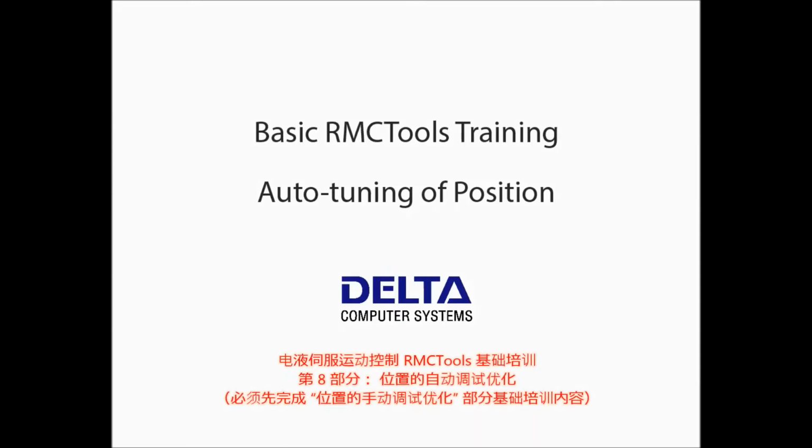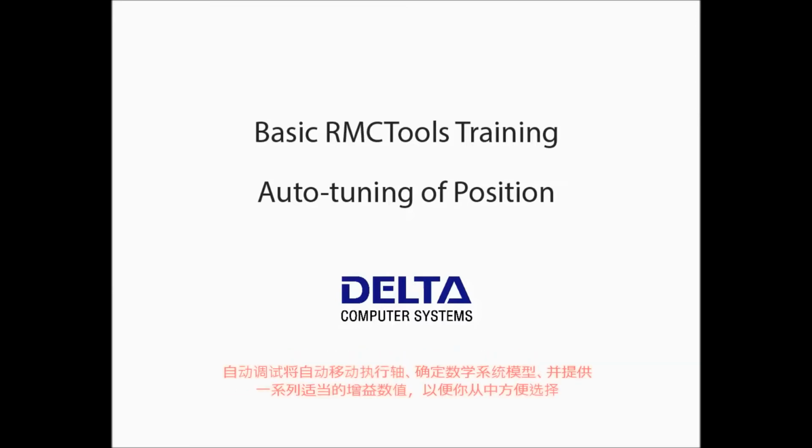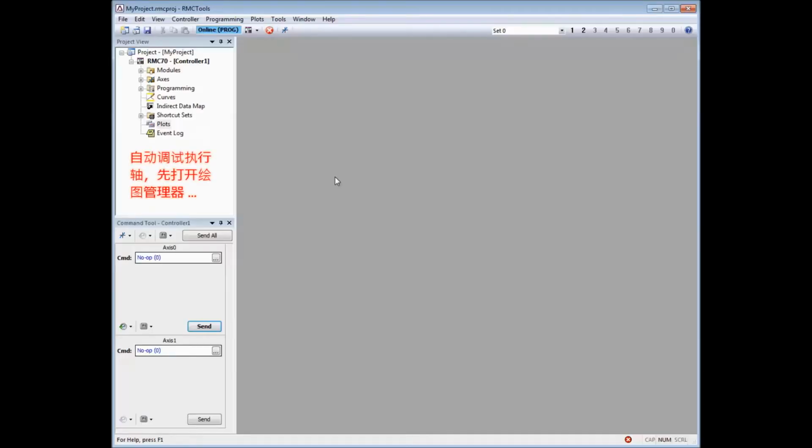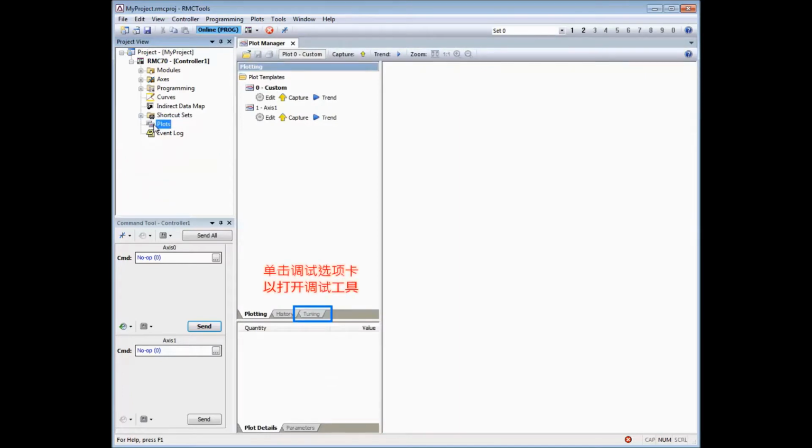Please make sure you have watched manual tuning of position axes. Auto-tuning will automatically move the axis, determine the mathematical system model, and provide a range of suitable gains from which you can easily choose. To auto-tune an axis, open the Plot Manager, click the Tuning tab to open the Tuning